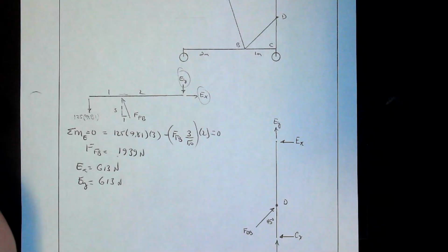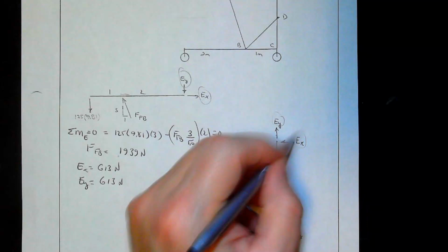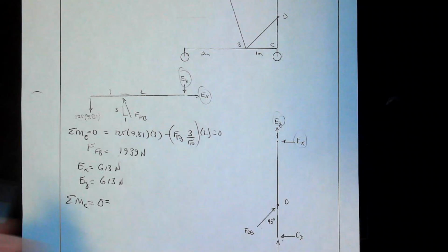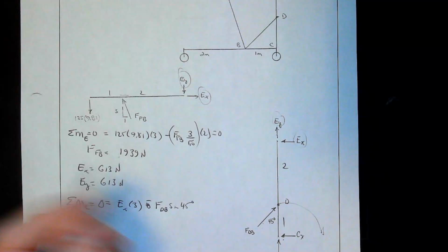So this problem by itself looks kind of intimidating. It's really not. So here's our free body diagram of the bucket. We have our 1,200-pound load. We're going to have the forces at the pin, which we don't care about. And this is a 2 force member, so it's very apparent that the force is coming down, and that's because that will then rotate about that pin and enable that bucket to stay up. So this force can't be going out that way.